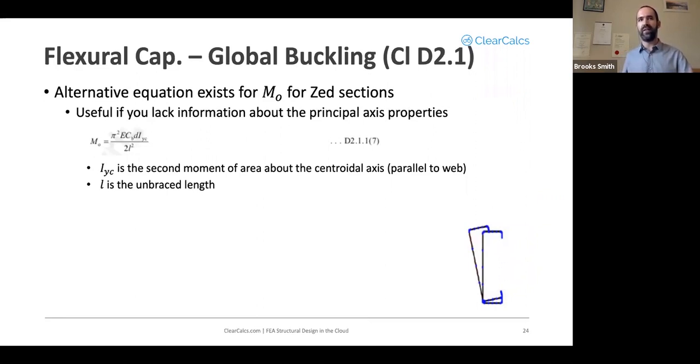There are examples of the types of bracing for lateral and torsional that are well described and well illustrated in the hot rolled steel standard. Unfortunately, AS4600 doesn't really provide much detail on that. But if you go to AS4100, the definitions are the same for what a lateral and torsional restraint are. So refer to that instead.